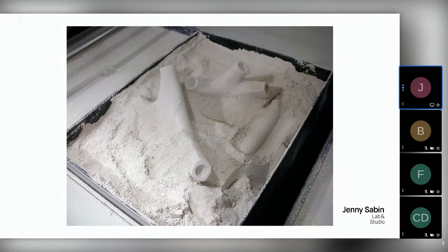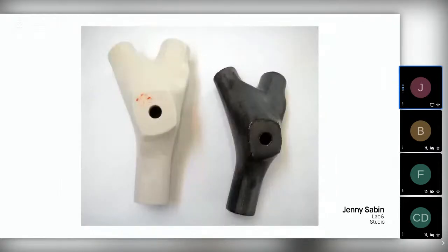And so what you see here is an image of our first successful 3D printed greenware clay parts. And this was the summer of 2009. And what I simply did was I took out the proprietary media, mixed up a high fire stoneware batch, a powder stoneware, with a bit of maltodextrin and sugar to facilitate the printing process, scrapped the cyanoacrylate adhesive and replaced it with a vodka water mix, as informed by some work by Mark Ganter, a mechanical engineer who was developing some similar approaches. And so this just absolutely blew me away,